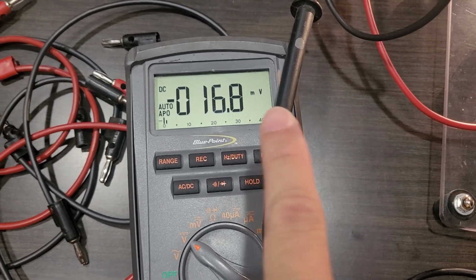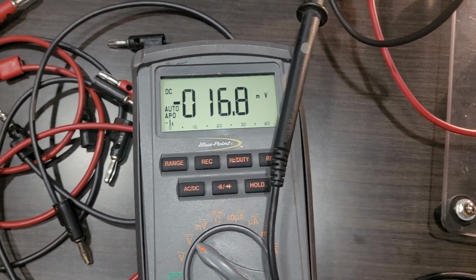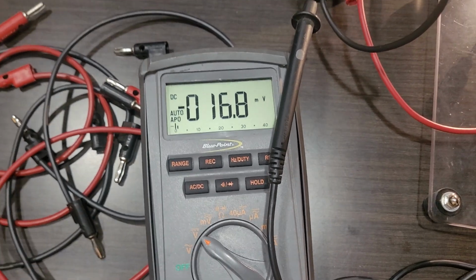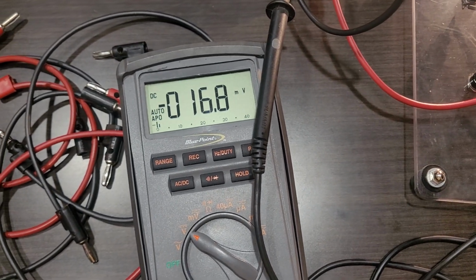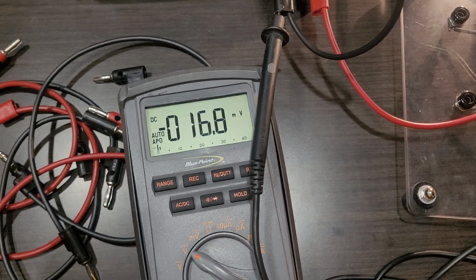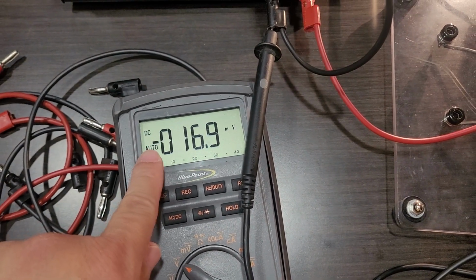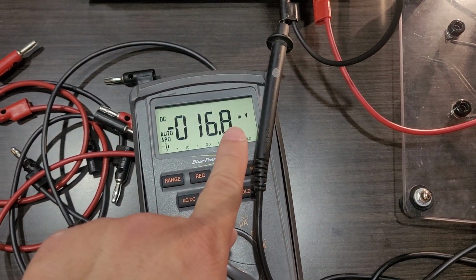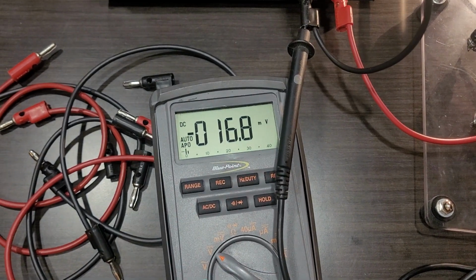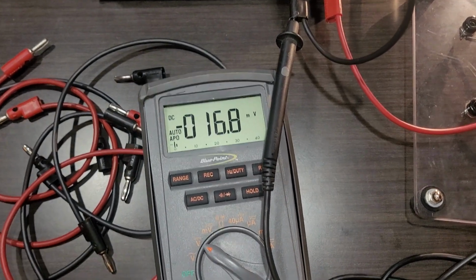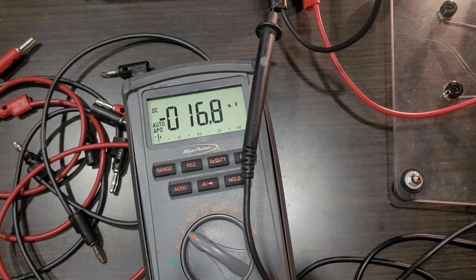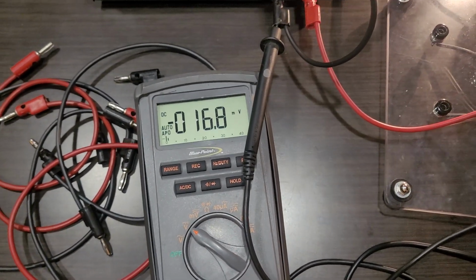This is millivolts. Again, keep them in mind, okay? Very small number. And the negative, again, just means my test leads are reversed, okay? So do not be alarmed. Don't need to write the negative, but you got to make sure you write the millivolts versus voltage because the millivolts represents a very small number versus a big number, which is a big difference, okay?